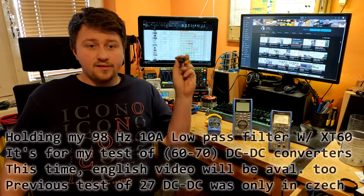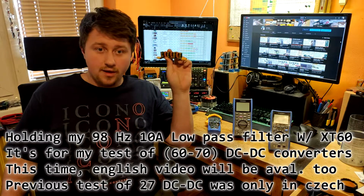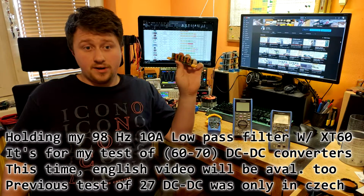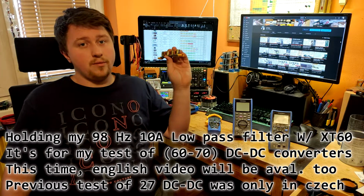Sine is also the most durable function. We can integrate or differentiate it and we still get the same function, only shifted a little in time. Any signal we pass through, let's say, a low pass filter may get distorted. Only sine never gets distorted. You can only have lower amplitude.